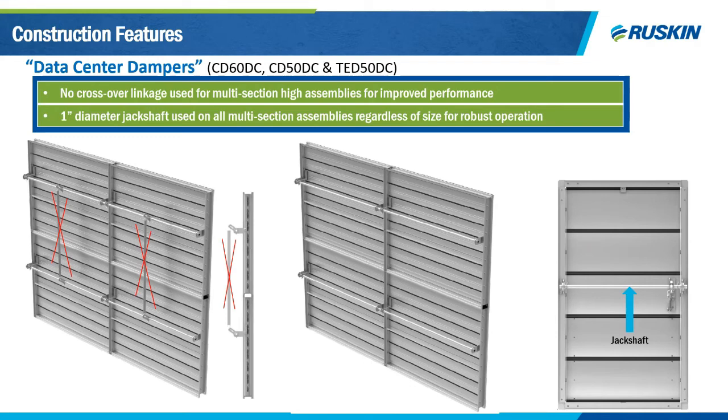What this will do is improve your damper performance because you have fewer moving parts when operated, which will also help the long-term life of that damper. There are lots of different damper sizes in these data centers, but we have standardized on a robust 1-inch diameter jack shaft that will be used on all damper sizes for the internal mounted actuators because we're replacing that crossover jack shaft linkage.